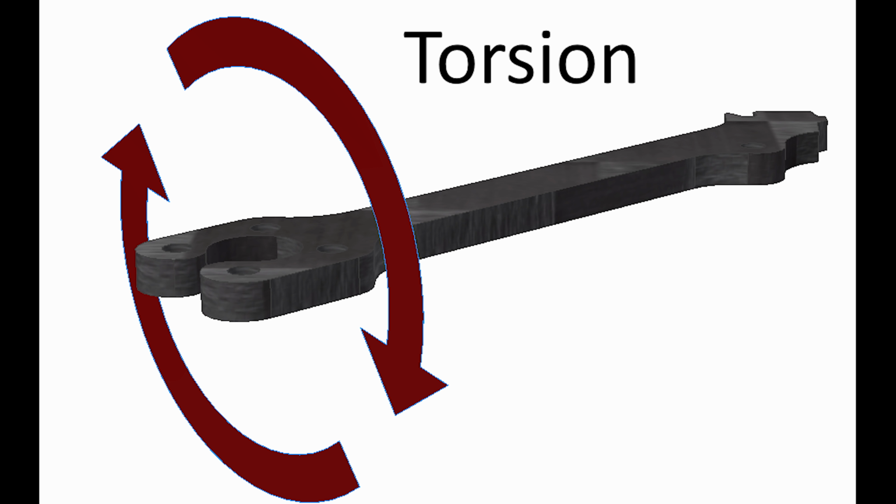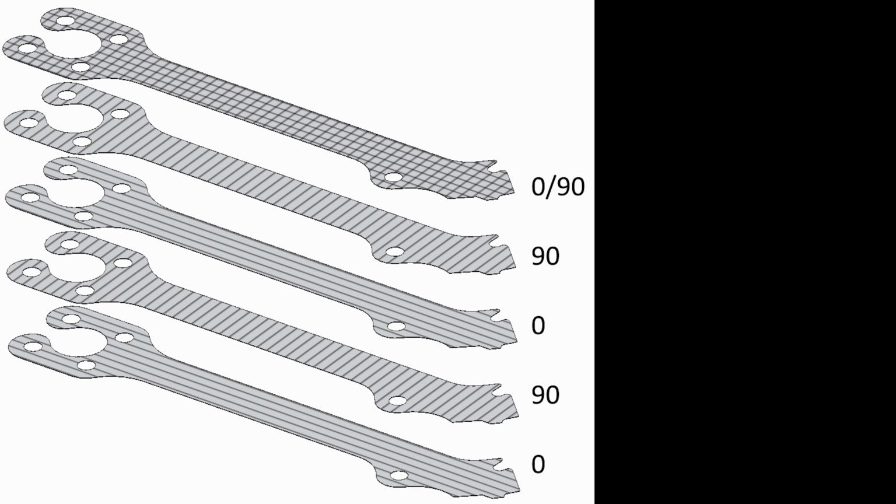Okay. Because to handle torsional forces, you need fibers that are plus or minus 45 degrees in your laminates. I can show you an example. So let's go over the actual laminates themselves and how they're typically set up. You have the picture of all the cross-hatching. While you get it, I'll explain.